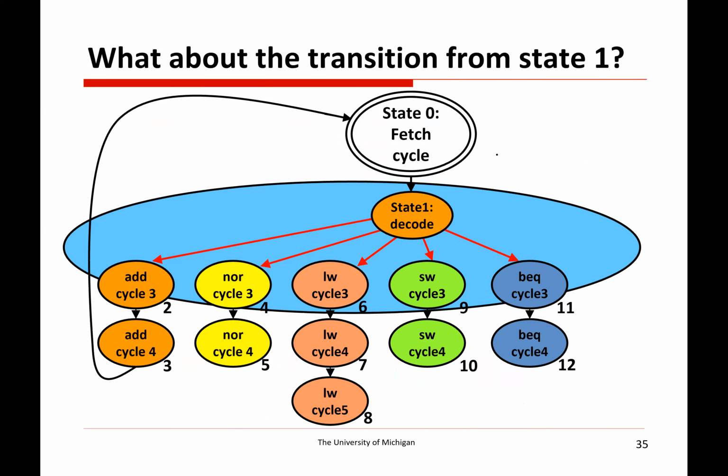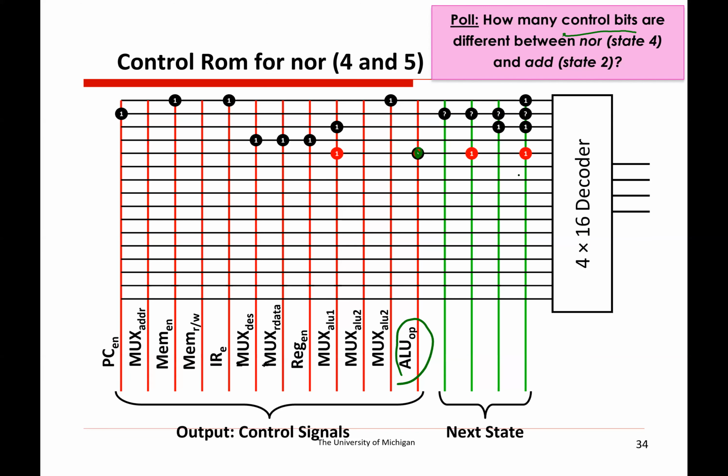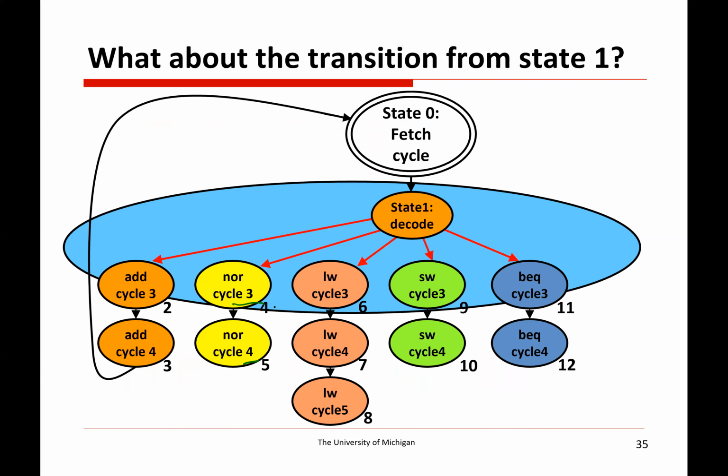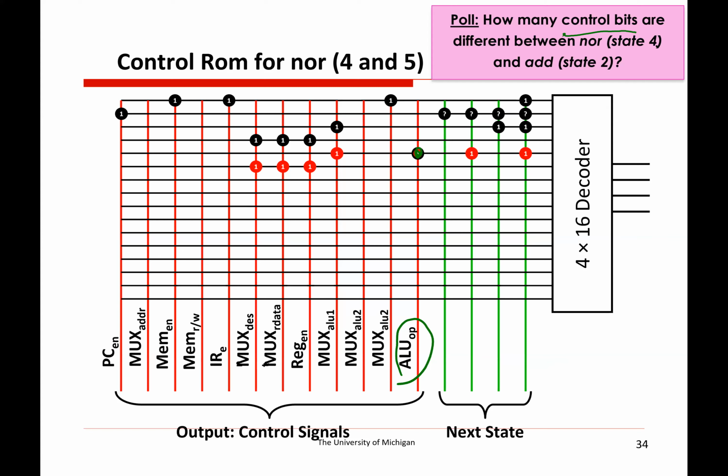And if we see here, we're in state 3, we're going to state 4. So we'll set this to be, well, that doesn't seem right. We're in state, oh, sorry. Yeah, this is state 4. We're going to state 5. So yeah, we're in state 4. So the binary encoding of that is going to have to be 5, which is 4 plus 1. So we put 1 and 0, this 4 and 1 bit set high.